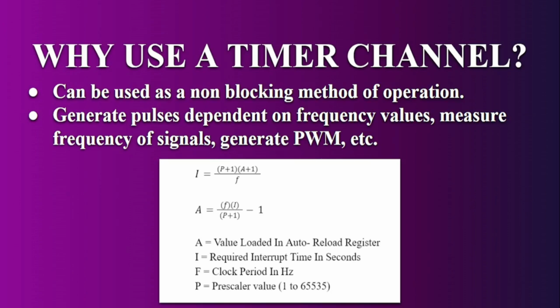And I don't want this to happen, as I need the UART terminal to continuously output the ADC values of my gas sensor, the battery voltage, and the actual voltage of the battery itself. And the only way to do this, as far as I know, is a timer channel, as it can essentially set the amount of time that the LED is going to blink on and off internally in the code with a clock source, not through the HAL GPIO write pin set and reset function along with the HAL delay that you would normally use when blinking an LED.